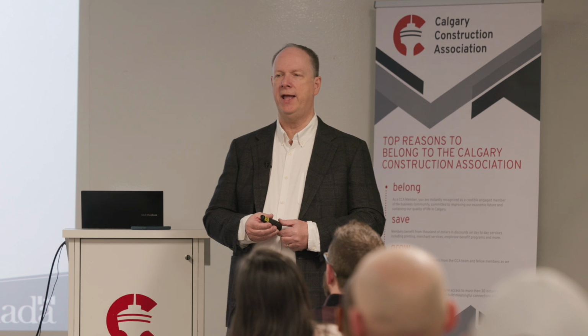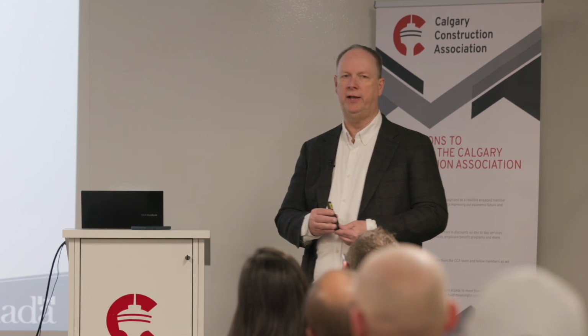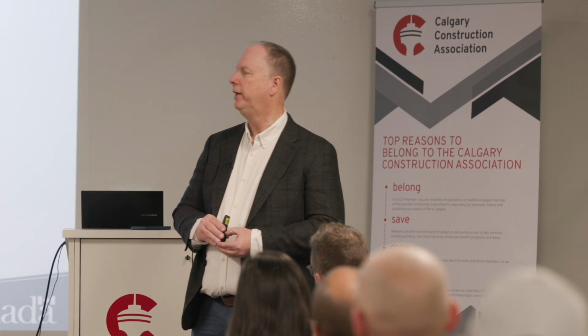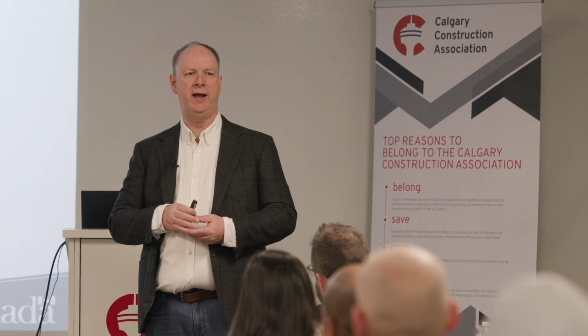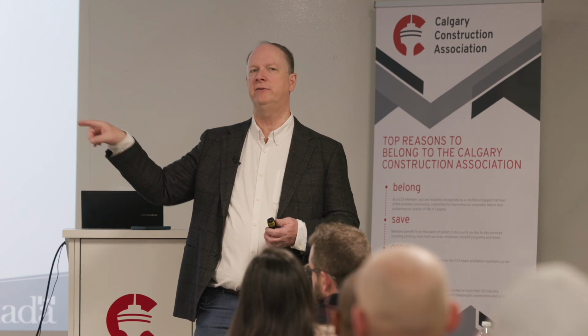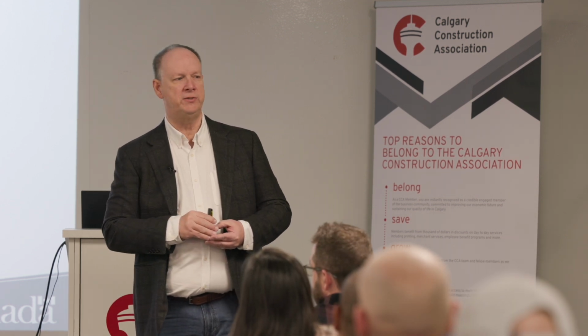So one of the things that we can do is there's a product out called AeroSeal. It is available from some of your mechanical contractors. They use a device just like this. It might actually look a little bit nicer because this is the last iteration of it. And what they do is they inject, and this is a technical term, people, sticky dust into the plenum. And this sticky dust finds all the eddies and all the gaps in your mechanical delivery system and seals them all. There's a couple of benefits.